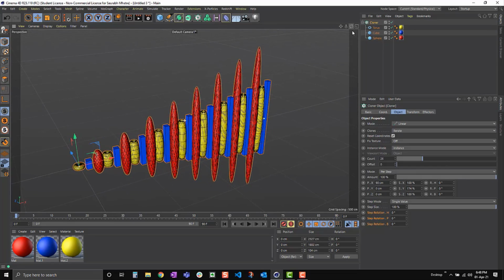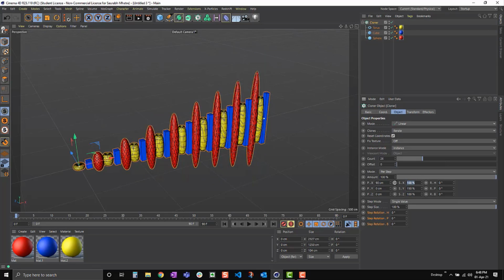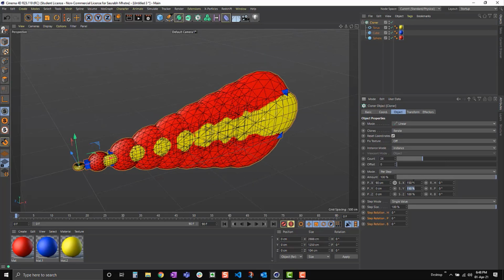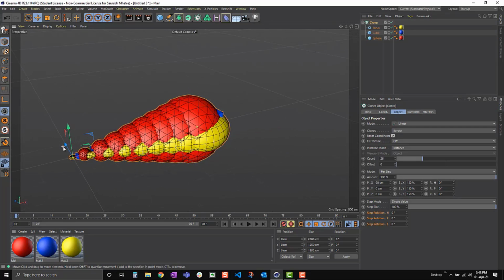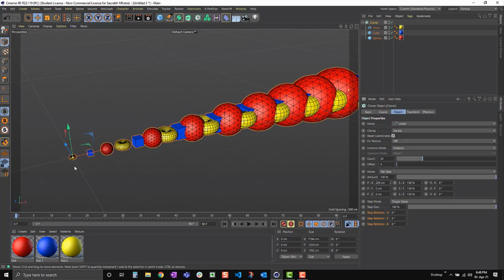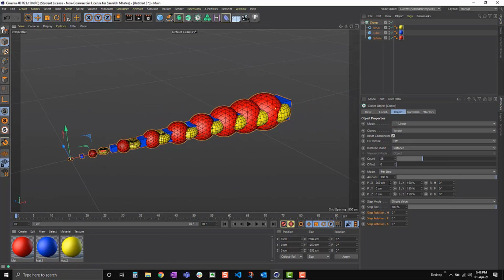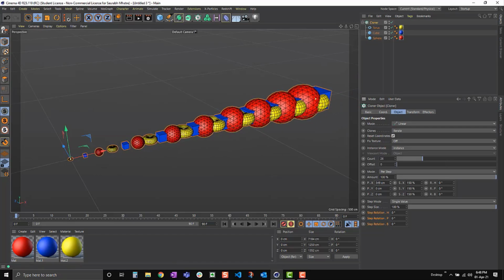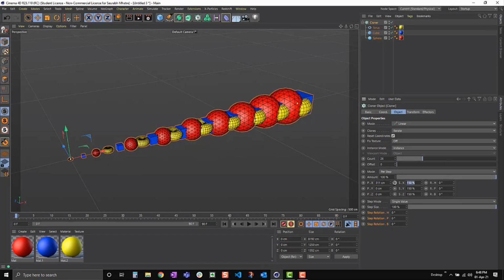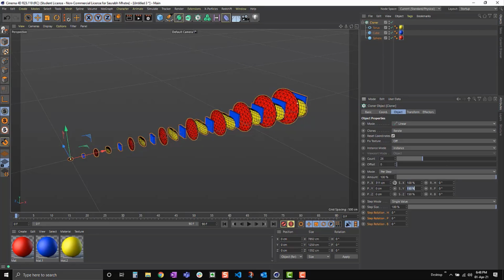See it in 3D. If you want to scale it uniformly, we can just say 150, 150, 150. So a lot of these objects have blended, so if we increase the size, the position, let's just turn this a bit down, back to 100.